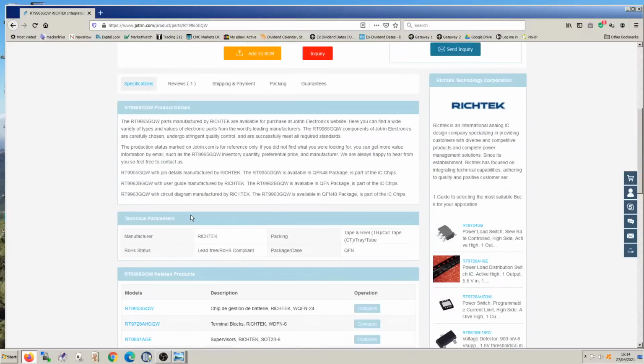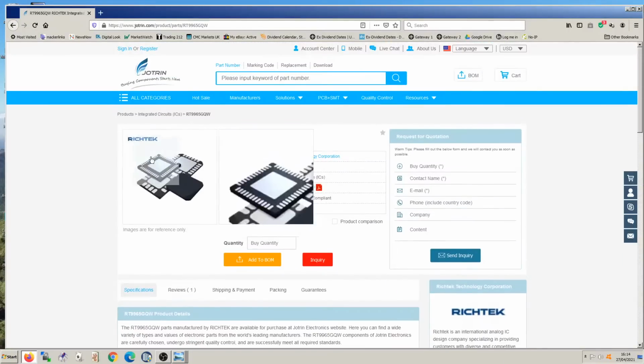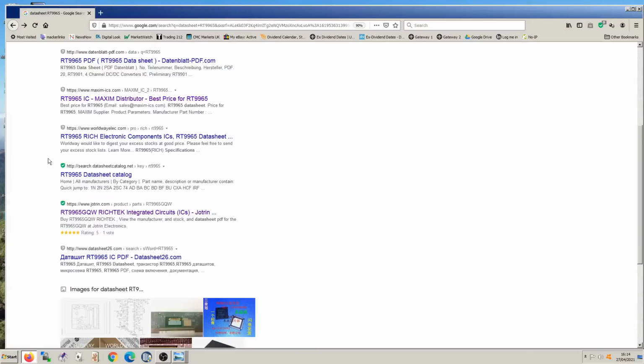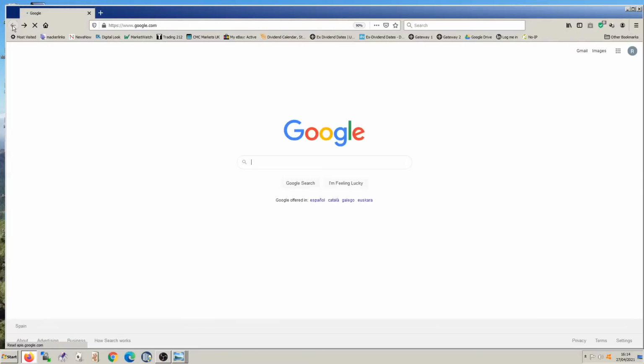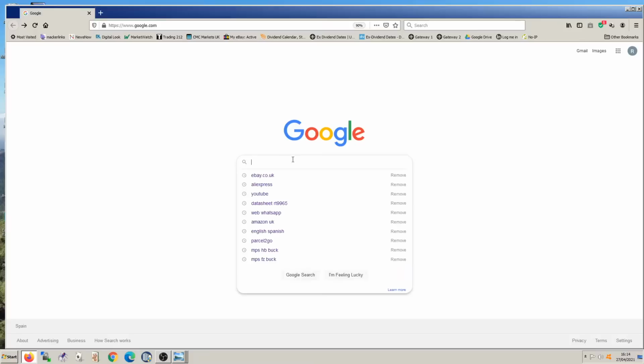No, I don't think we're going to find a data sheet for this chip, but as I say, I do believe that's working. Maybe we'll get to look at gamma IC faults, so we have some more monitoring with a faulty one. You'll see what I'm saying. Normally what happens is the voltage should be in an ascending sequence, and one is way out, and usually you get a very bad contrast picture or something like that, but you do get a picture. Let's look at the other one. Don't hold out much hope for this one either, to be quite honest.